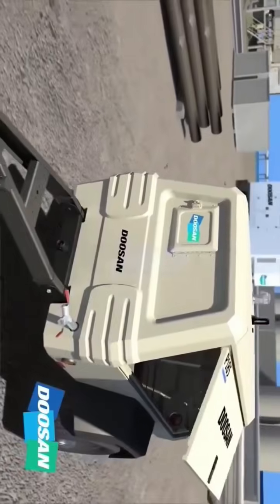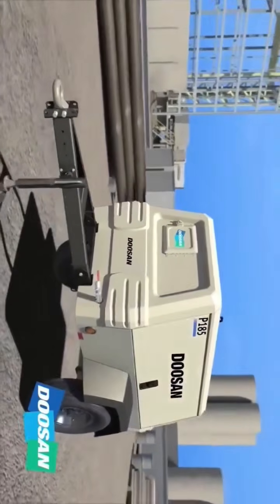Back at the separator tank, the air is almost ready for use. Air exits the pressurized tank and passes through an element filter which reclaims most of the remaining oil from the airstream. The air is then piped out of the compressor to the service air valves where it can be used for thousands of applications.